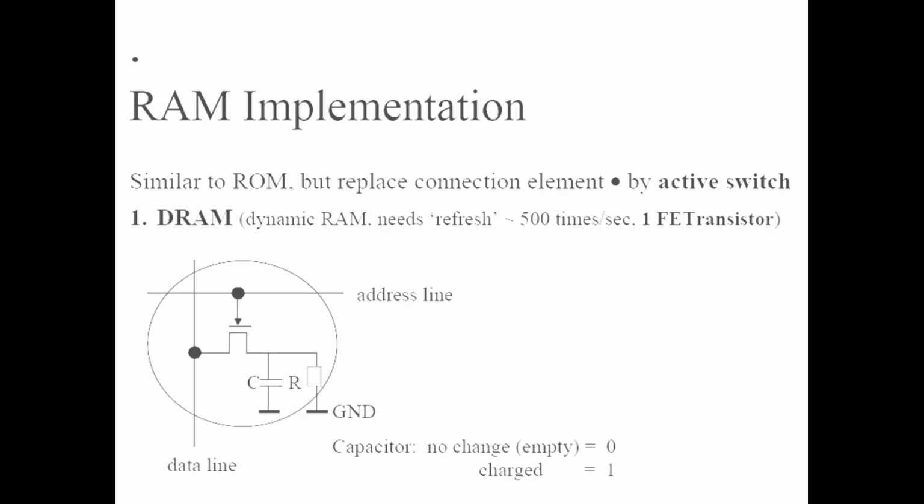As for the advantages of 1T-DRAM, we have the following: high density, only one transistor and one capacitor per cell, allowing for high density memory arrays; cost-effective, fewer components per cell, reduced manufacturing costs. As per the challenges, we have leakage and speed. Leakage, the capacitor loses charge over time, necessitating frequent refresh cycles. As per the speed, the need for refresh cycles can impact the overall speed of the memory.